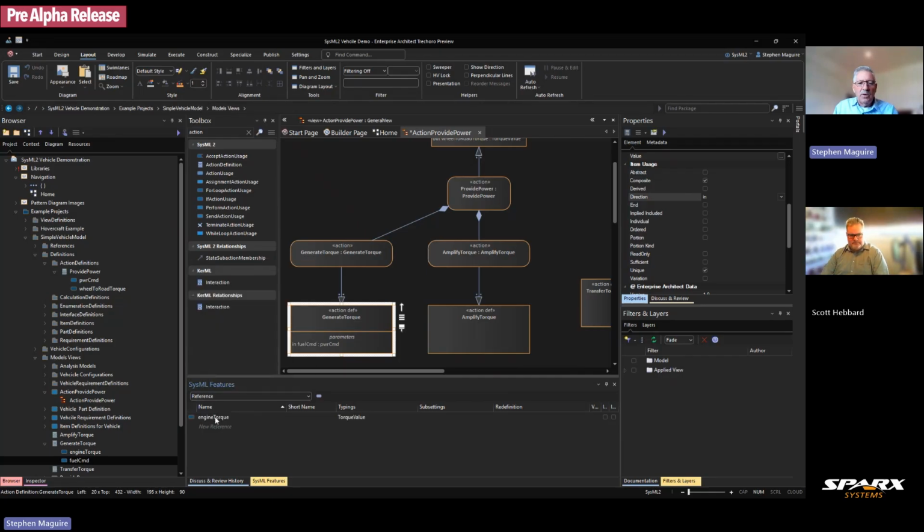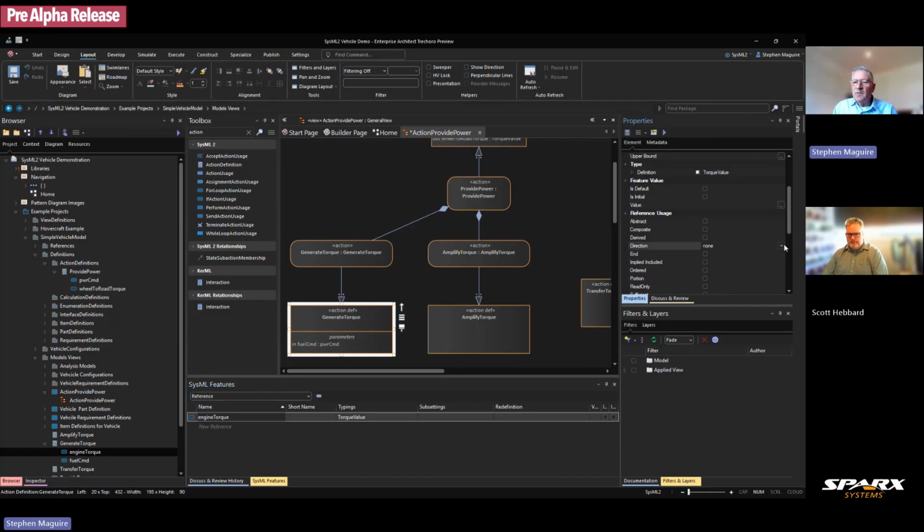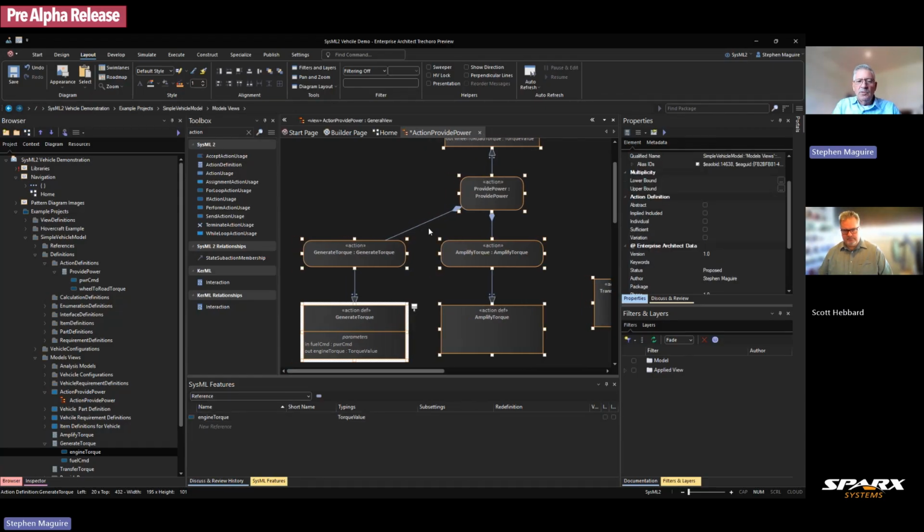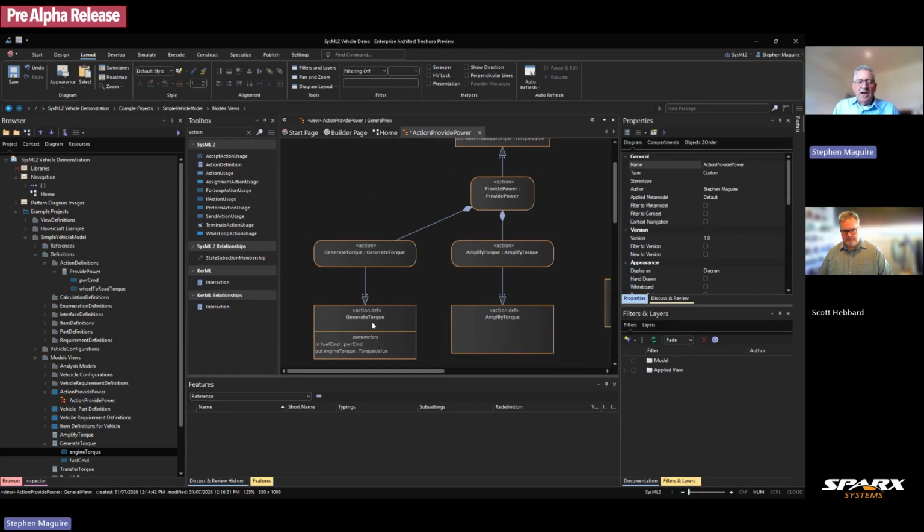So we can go references. Well, this one's an out one. So again, let's select out there. So do they just default as none? They default to none because it's just a reference until I tell it that it's got a direction, and that makes it into a parameter. So if I had put in the compartment visibility as reference or item, then they would have shown up there. Yeah. Right. But look, and again now, I'll just multi-select everything, move them over a little bit. Now I just do exactly the same thing.